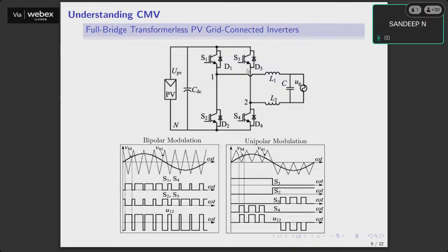right? You have field poles that generate the flux, which gives your MMF, which is constant. It keeps on rotating at synchronous speed, and then it induces EMF, and all those things happen. That MMF is moving very freely in the air gap, and that is the reason we have a very smooth sinusoid being generated. Because we know that any sinusoid can be represented by a rotating vector, that is nothing but a phasor. So in a generator, the reverse is happening. You have a phasor that is rotating, so we are getting a sinusoidal waveform. It is exactly the reverse.